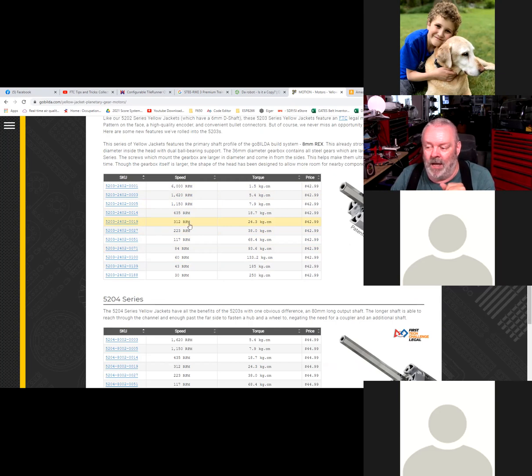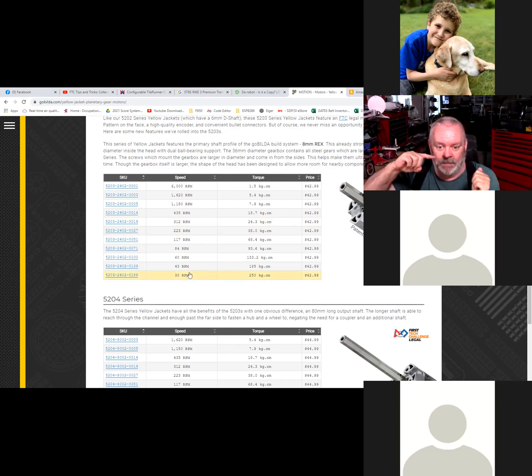So it tells you that without a load on it, it turns about 312 RPM. Great. You can get different gear ratios of those motors all the way up to 188, and it'll do about 30 RPM. In other words, it'll take 2 seconds to make a full revolution, which is pretty slow, and it's really quite strong. Yeah, it has more torque, more torque at low speed. So you've got some options there.